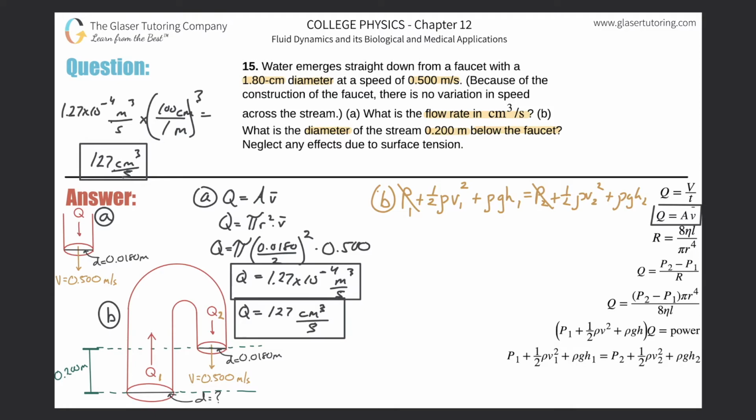You also will notice that we're talking about water, and the density of the water isn't really changing. Remember, in theory that's not true, because we've done problems in the past where we were talking about the density of seawater at the bottom of the Marianas Trench, 11 kilometers down, and we realized that it actually does change, okay? But in this problem, the density change for water from this location to this location, we're talking about 0.2 meters, is basically a non-event, all right? It will not influence your values in any appreciable way considering significant figures. So the densities are constant.